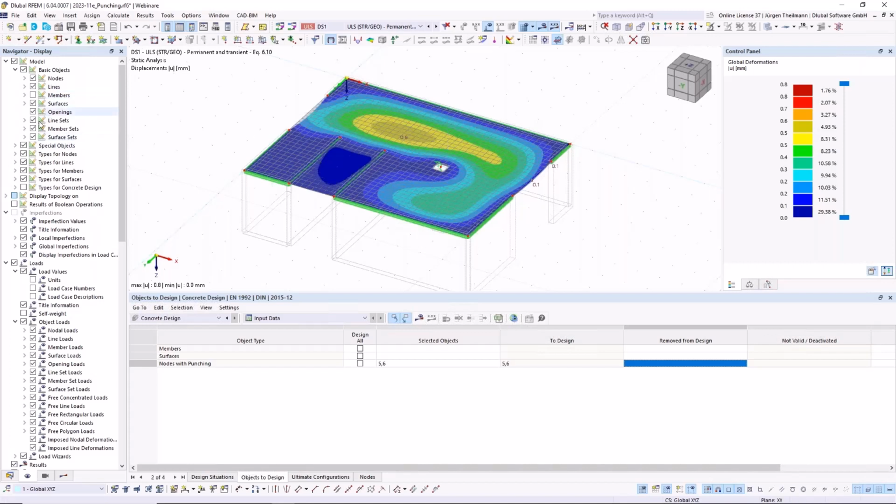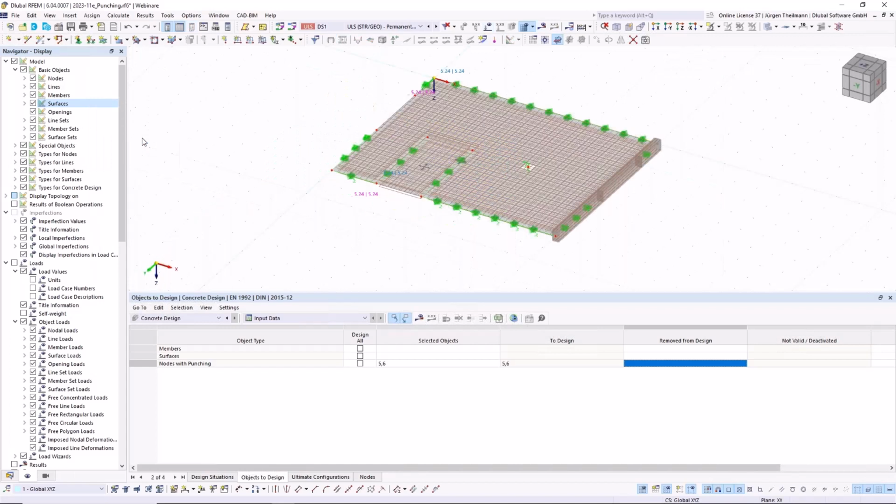And another, if this is not the case and it's not so easy to spot, you can always do a right click on that navigator display and set all your display settings to Dlubal standard. And then the members will get activated as well.